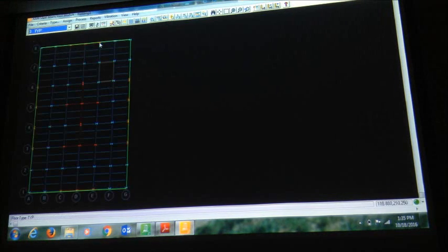Actually, I'm designing it, but I'll have to change it now. Your beam designs are done. Okay, I just want to change. Steel codes: LRFD, LRFD. Good. 360 means our 14th edition. Remember chapter 16.1 dash something? That's actually AISC 360-10, that's the specification. Still defaults, those are fine.